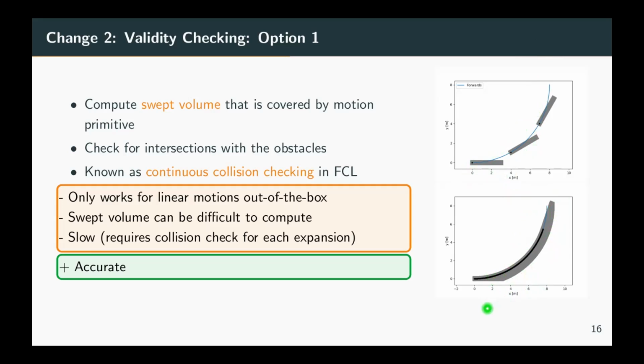Now you might note that this collision shape is unfortunately not convex, it's concave, because if you take any 2 points, like this point and that point, then the line between the 2 points does not lie inside that collision shape. So that's not so great for collision checking because it's going to be slow.